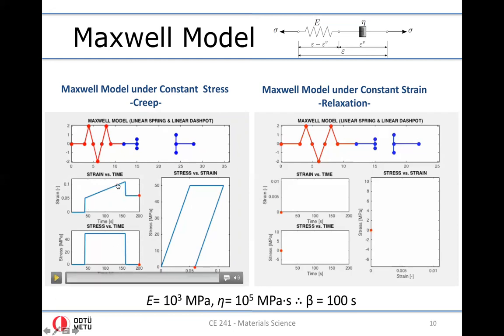it is. So it would be more instructive if you follow this movie with the animation of the deformation of the Maxwell model. Let's play it again. Instantaneous elastic, dashpot opens. You see spring is stationary, spring recoils, and dashpot remains where it is.